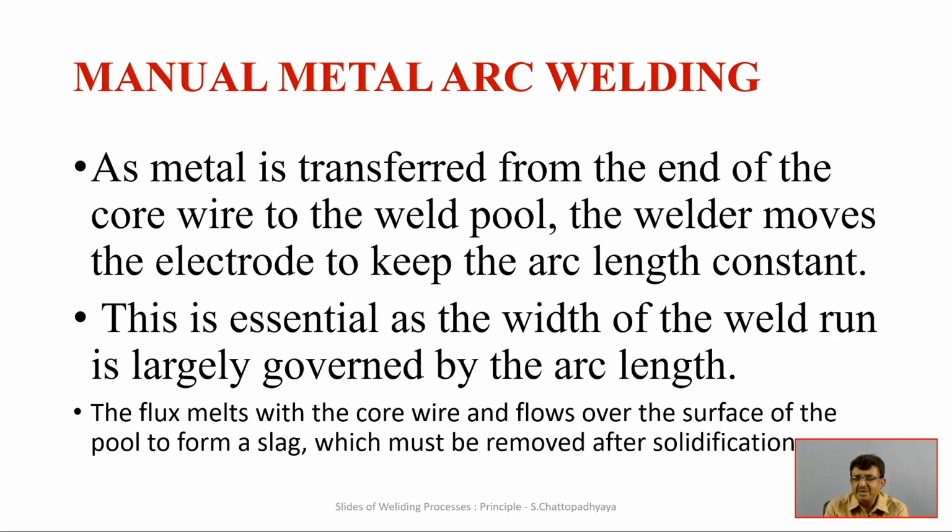So there are different bead geometry features: the bead width, the bead penetration and the bead reinforcement, and all of these are important bead geometry parameters. After sectional cutting, people know these bead parameters, and these parameters have a very important relationship with the process control parameters of the welding process: voltage, current, and travel speed.